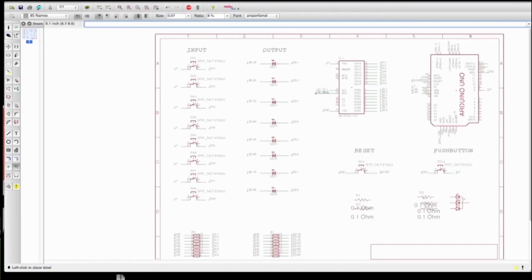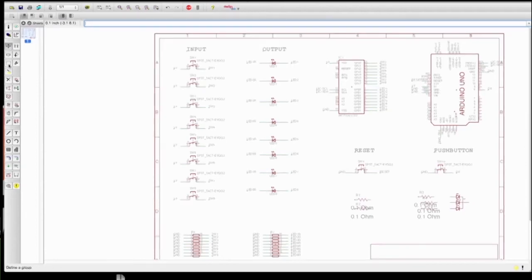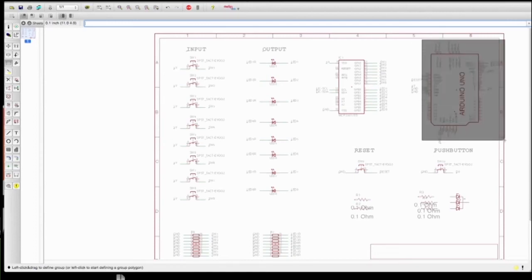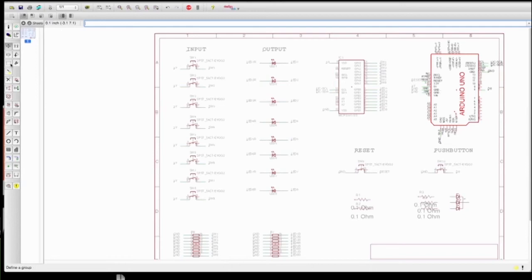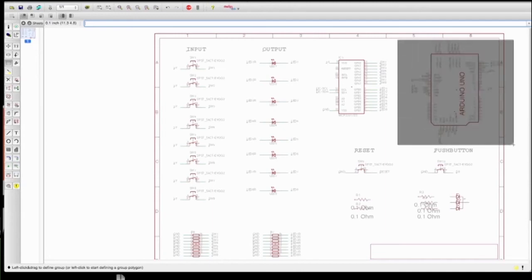We still have to do one more thing with the I2C bus because we want to bias the voltage high, although it probably wouldn't matter as much on the current board because it's not really going anywhere. All right, you see, this is going to drive me nuts. This would work perfectly fine, but I have to rearrange the Arduino because these labels are off the edge. And I didn't get everything, so let me go back and do it again. I want to move.